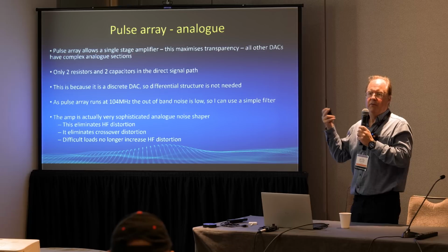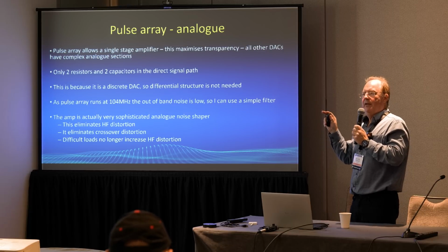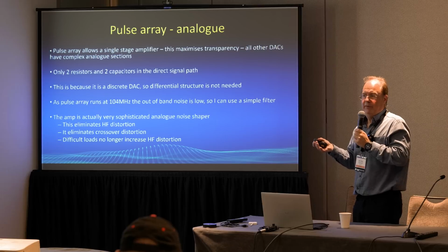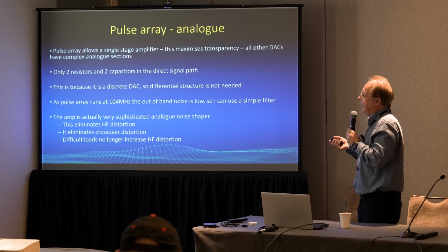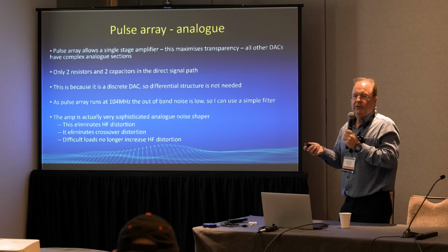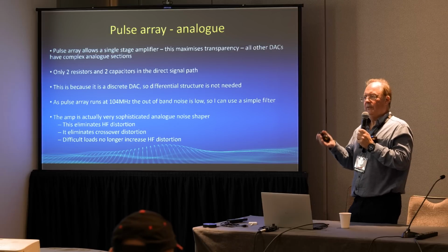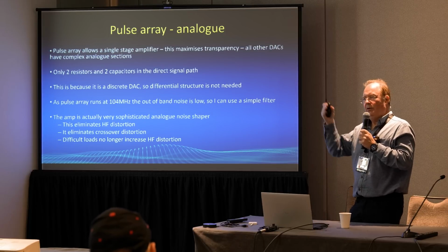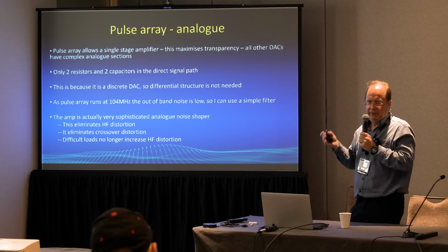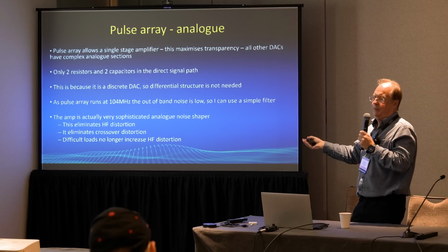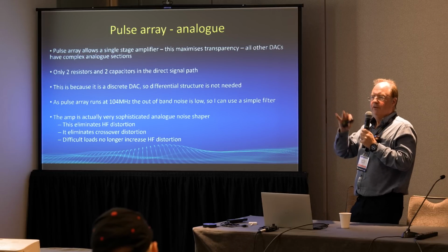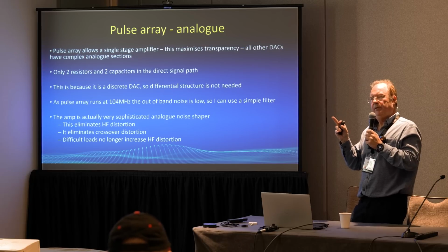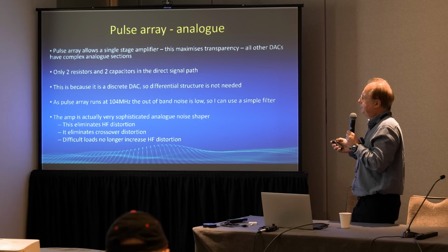This is because running at 104 megahertz means that the noise level at 1 megahertz is actually very low. That means I don't have to have a complicated filtering section. It's single-ended, it's not differential. Conventional DACs are differential. You have a positive output and a negative output. You then have two sets of I2V converters. You'll then do a differential to single-ended converter. You'll then have an output buffer. Lots of analog complexity, lots of amplifiers. With mine, it's just one amplifier that's capable of driving headphones directly.